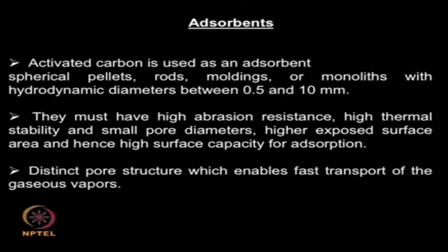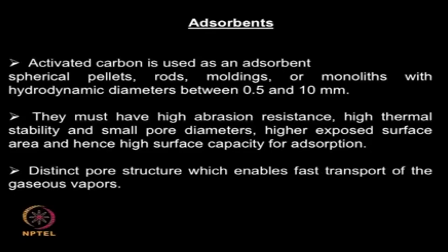When you are buying an adsorbent material or when you are designing an adsorbent material, you have to keep these points in mind. All the adsorbent materials have good pore structures, some of them have very uniform diameter pores, and there is a lot of research done in designing these pores of uniform diameter. You do not want a very large distribution of diameters, that means very small diameter pores to very large diameter pores. If you have very small diameter pores, sometimes the gases might not enter, so those pores become useless.